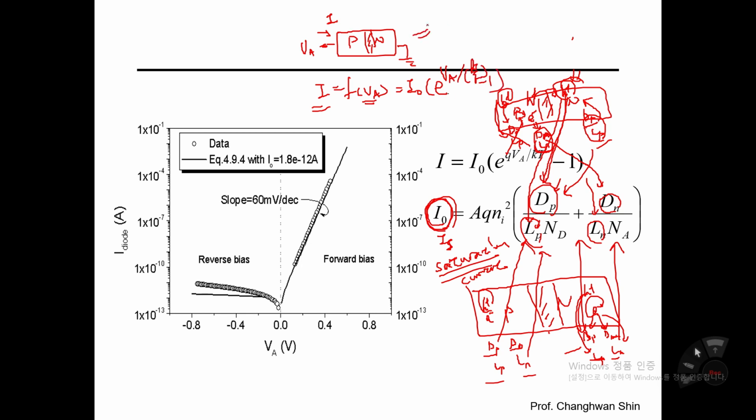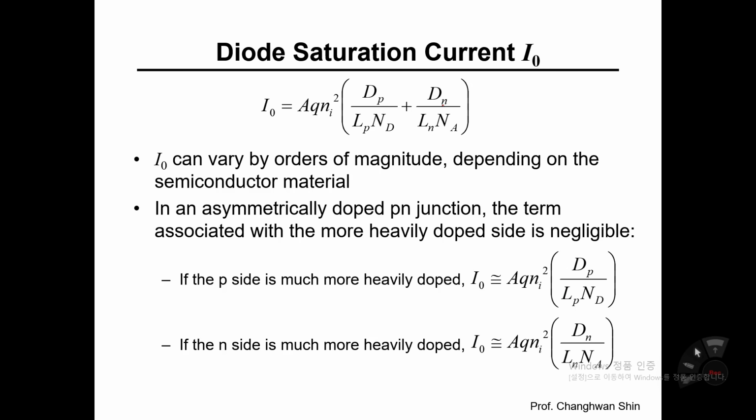Okay, so instead of this figure, if I'm using the circuit symbol like that, plus minus V, and current is flowing in this direction, following the passive sign convention, as you know. For a given resistor R, I is a function of V: 1 over R times V. Very linear relationship. But in a diode, the voltage-current characteristic is very non-linear. So once a diode is included in your electronic circuit, that circuit is named a non-linear circuit. But if your circuit is built up with resistors only, then people say that this is a linear circuit.